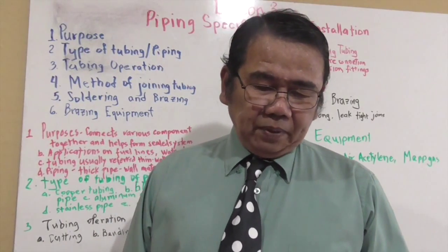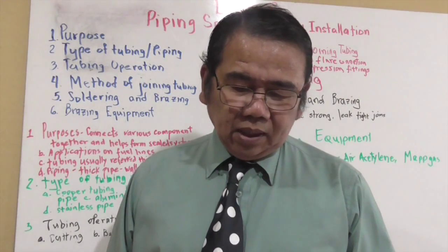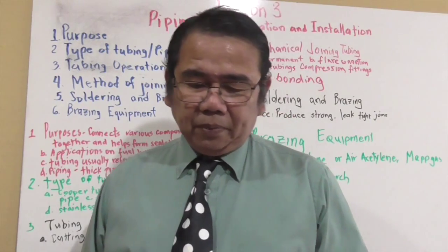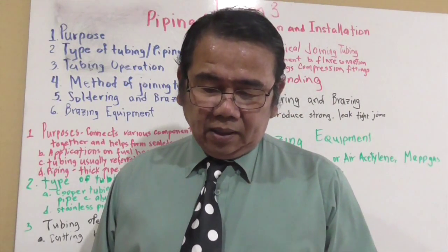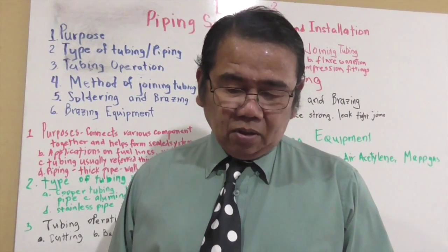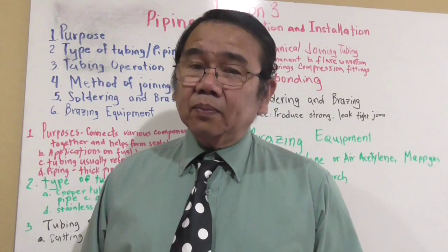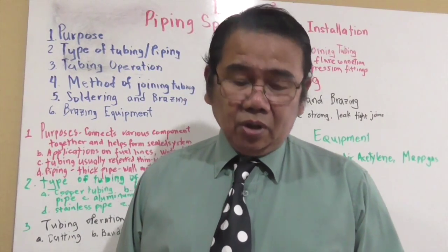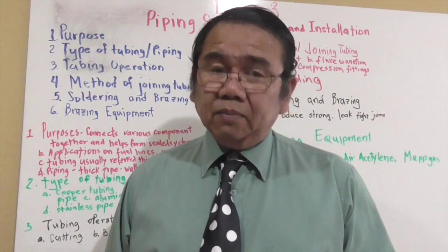Most common with copper and aluminum is the handheld tubing cutter. It may be obtained in different sizes. A model to cut 1/8 of an inch outside diameter to 4.25 inch outside diameter. Position the cutter on the tube at the proper cutting point.